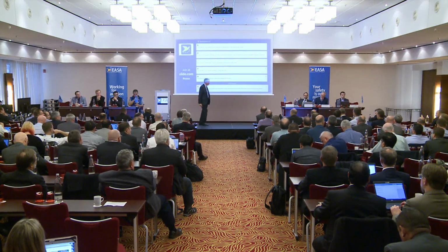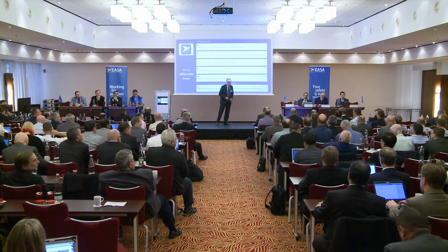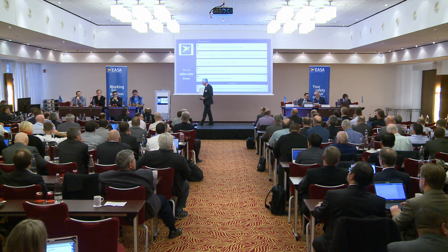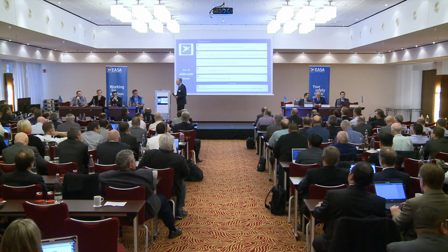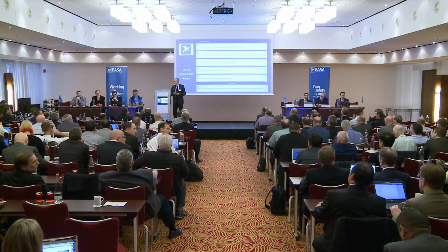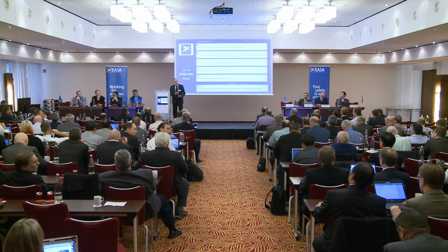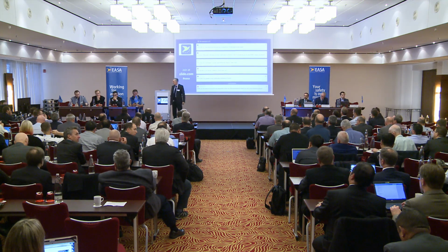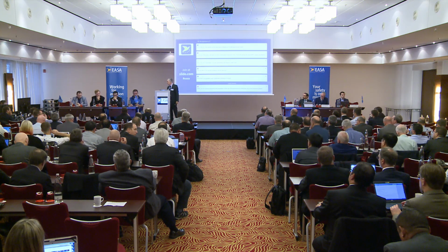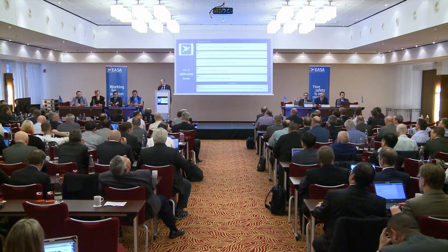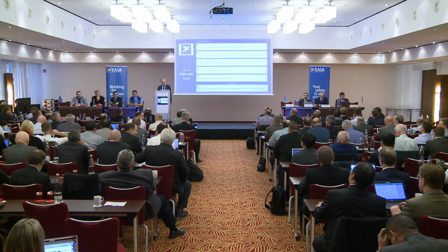Hello, I'm Patrick Lantery, a flight test pilot. I have a question on the MI-171. On some slides, the tail rotor is located on the right-hand side, and on other slides, the tail rotor is located on the left-hand side. If it's confirmed that the tail rotor is on the left-hand side, meaning you changed the design from the previous version, you will have interaction of the airflow with the tail. So in this case, what is the reason you changed to the left-hand side location for the tail rotor?